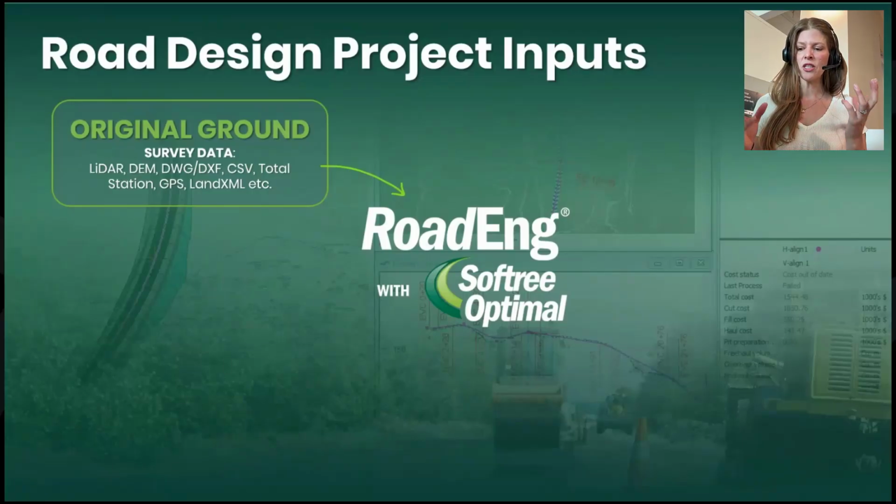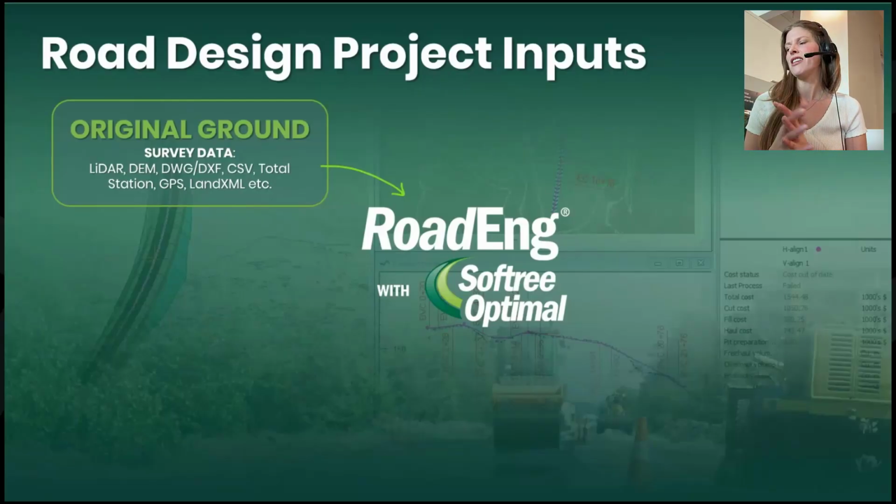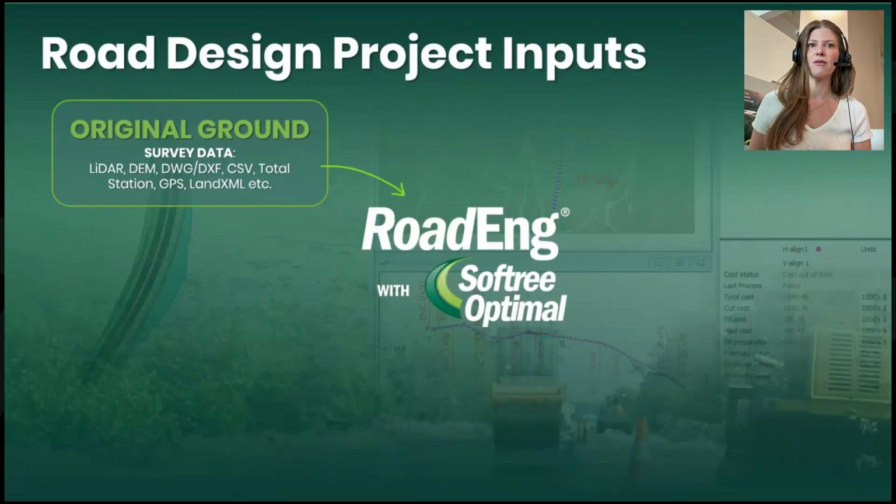So here we're talking about being able to import your survey data. That can come in a wide variety of formats, whether that's LiDAR, DEM, DWG, DXF, CSV, total station, you name it. We basically need some type of data with elevations, and that's going to go into RoadEng. That's going to help build our DTM to represent our original ground.